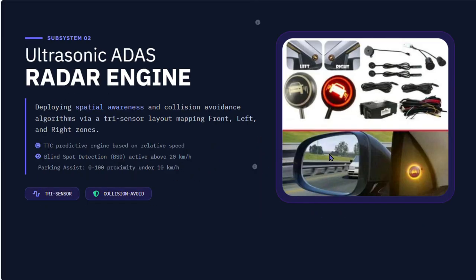Ultrasonic ADAS radar engine. Moving to subsystem 2. We have an ultrasonic sensor radar engine that handles precise spatial awareness using three sensors configured to track obstacles around the front, left and right segments of the vehicle. A common pitfall in basic warning systems is relying strictly on a fixed distance value instead of a design time of collision